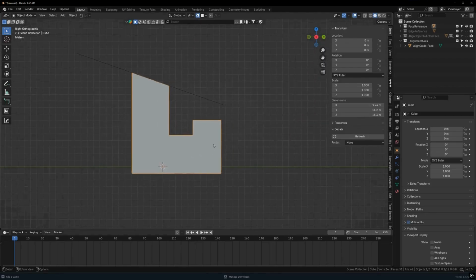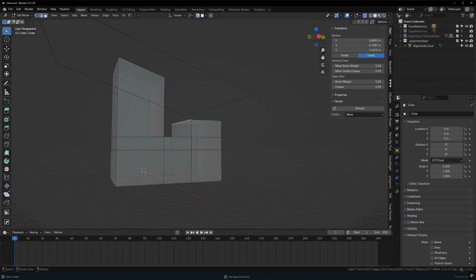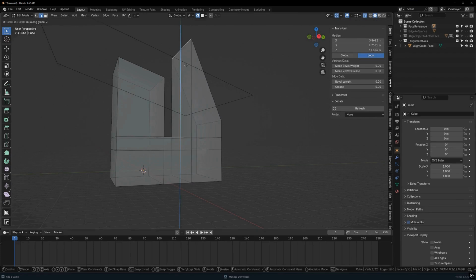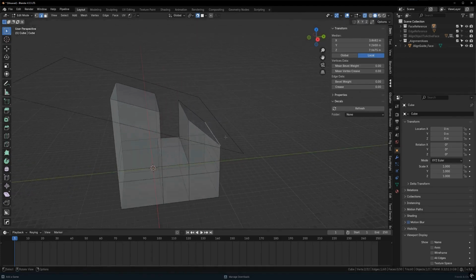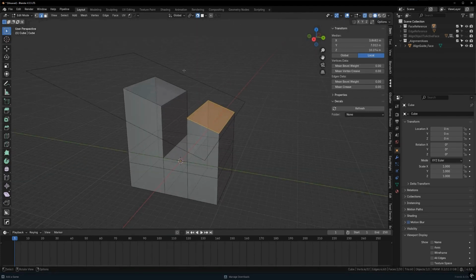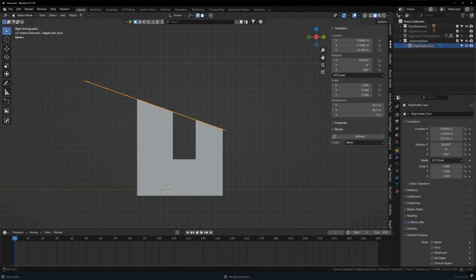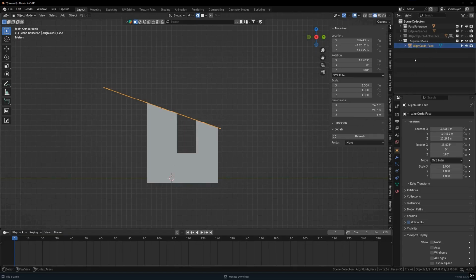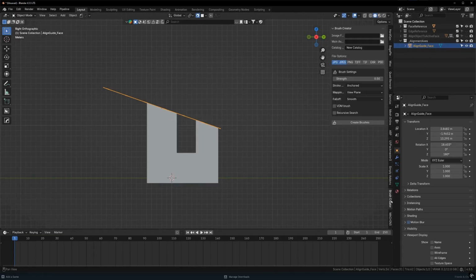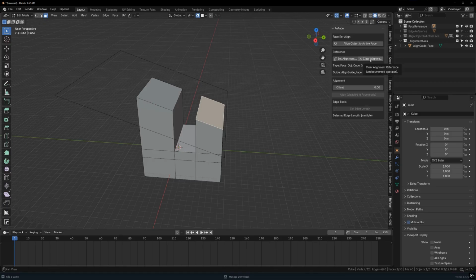So what this does is it automatically sets the snapping mode to face mode and activates it. So if I go and then constrain it to the z-axis, yeah, you can see that it snaps it to this face. I can go here, and now this face is coplanar to our main face using this reference plane. And then you can delete it by either manually deleting it from here or using the N panel. Go back to edit mode, go to ReFace, and then you can use clear alignment.